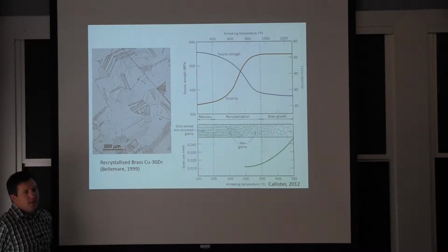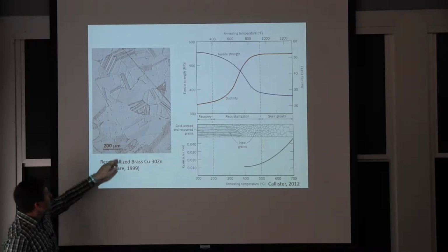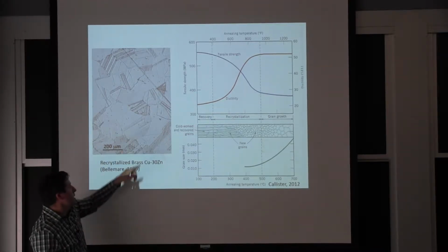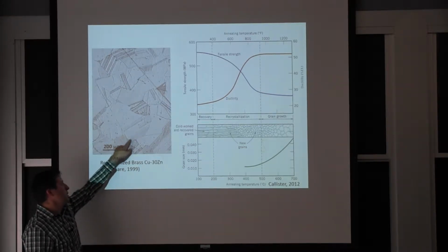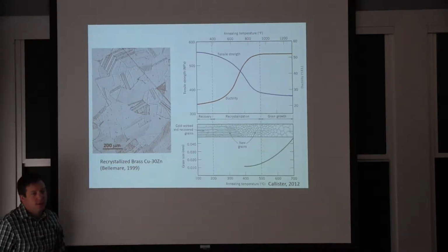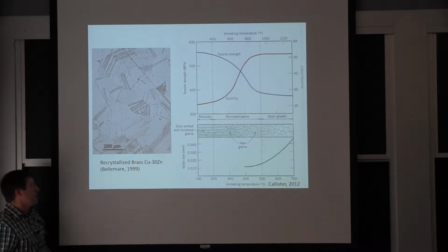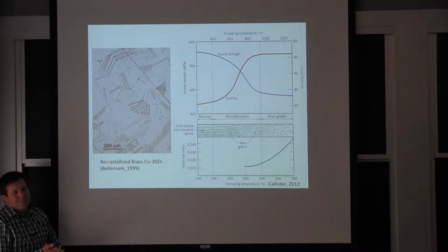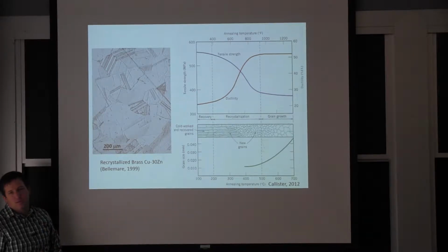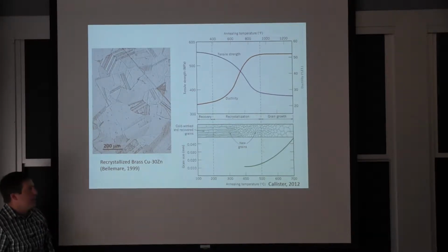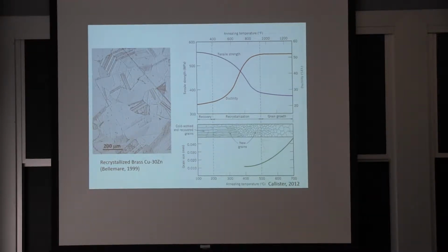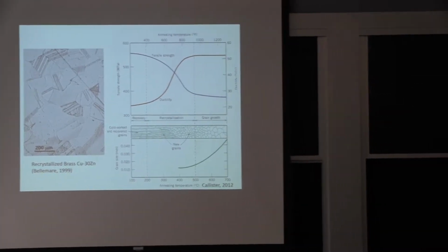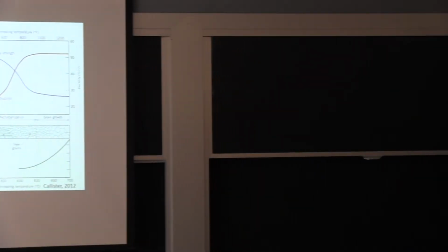So it's essentially a relatively low energy interface where you have a change in crystallographic orientation, but it's not a grain boundary. The grain boundaries are very high energy, they're very disorganized, and the twin boundary is really more or less a reflection of the crystal structure. The reason for showing this one, it is a single phase in this case, and it's nice to have some idea of size.